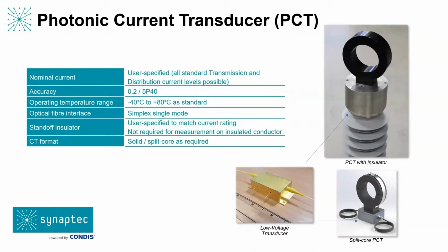It requires a local power source. The actual method of the measurement is very different because the measurement is encoded in the polarization of the light, and it can only reach a distance of somewhere between 10 and 20 kilometers typically from the actual merging unit. So the physics used in our device encodes the measurement in wavelength, which is a lot more robust to things like electromagnetic interference, which means we can operate over much longer distances than the NCITs typically can.